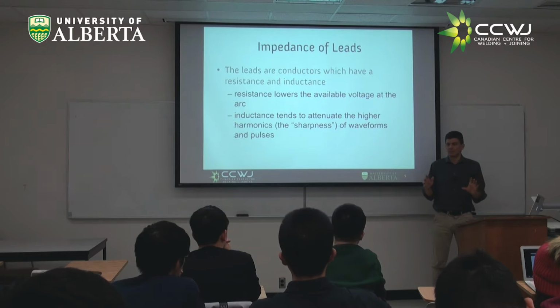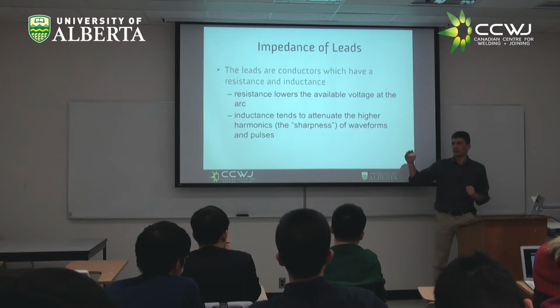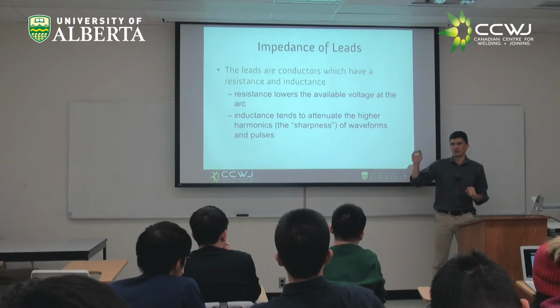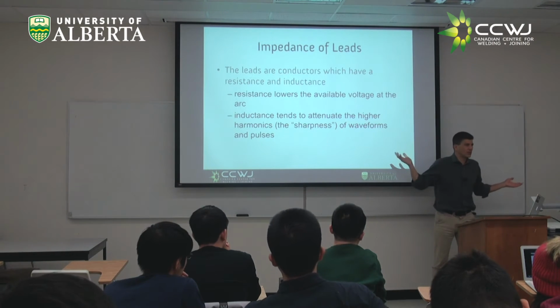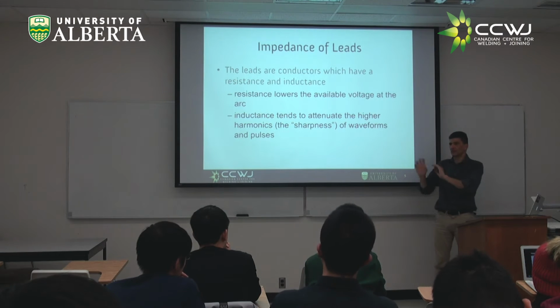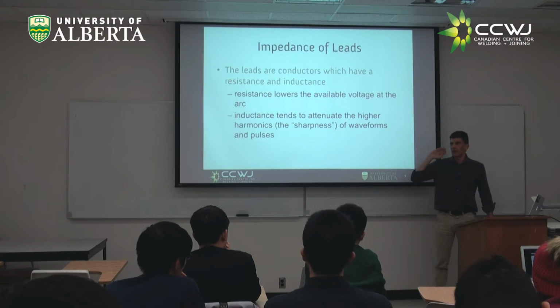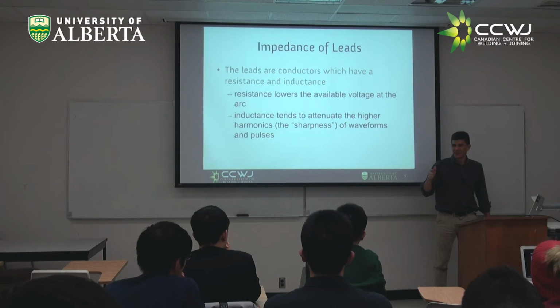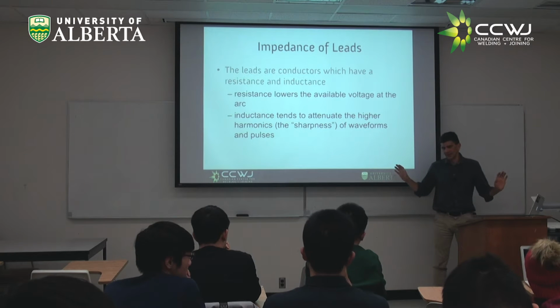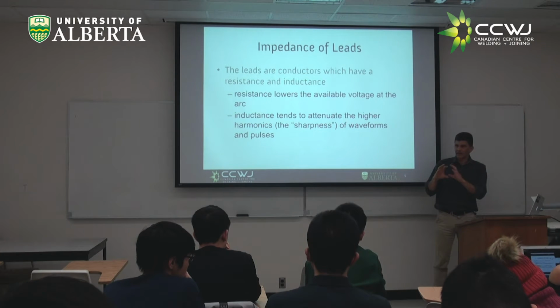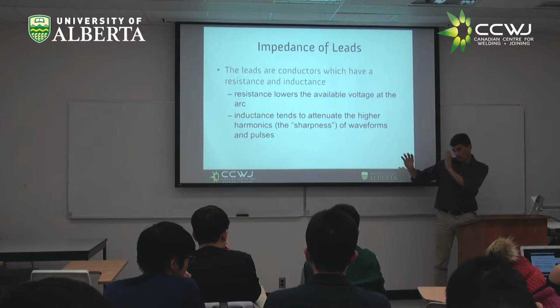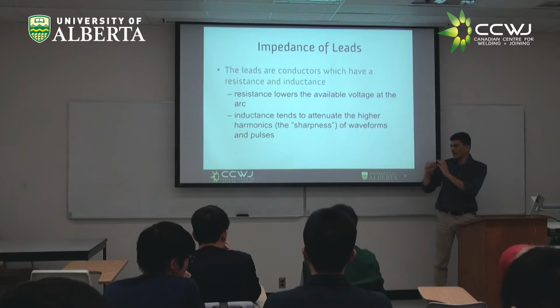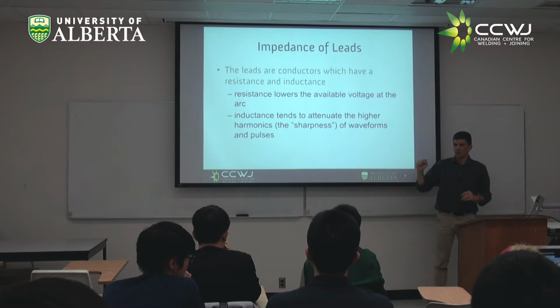If I have DC, constant current, do I need to worry about the reactance or the inductance or the impedance? No, because I'm not changing, right? It's all good. If the ball is moving fast or slow, I don't care. It's just going. Now, if I have a waveform, yes, right? So this is an interesting concept. Resistance in the leads is a problem always. But this reactance or this inductance is going to be a problem only when I'm trying to change the current in my welding machine.